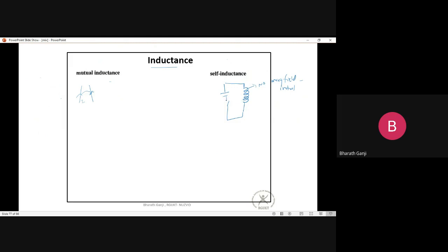So when you close the switch, slowly the current starts to increase, but it cannot change instantaneously. Initially, before closing the switch, the current was zero. When you close the switch, can I have 3 amperes of current? No, you cannot have such a big amount of current, because that means the current changed instantaneously from 0 to 3 amperes, which means the magnetic field inside the solenoid is created instantaneously. You cannot create a field instantaneously. Any kind of field creation takes a finite amount of time, right? So in order to have a field which can support that 3 amperes, you need to do work.